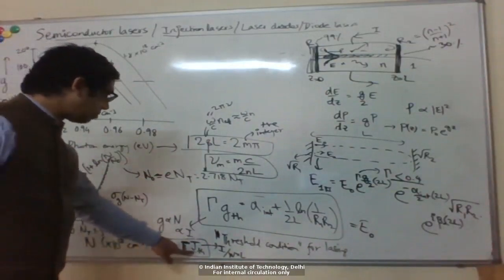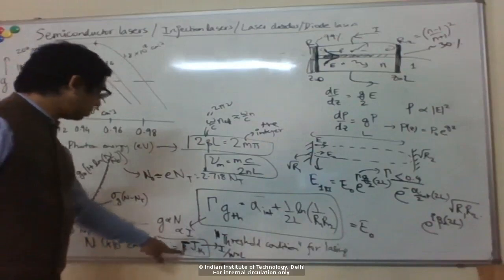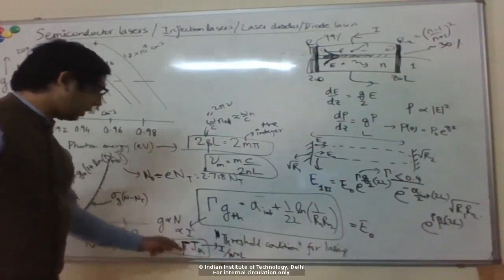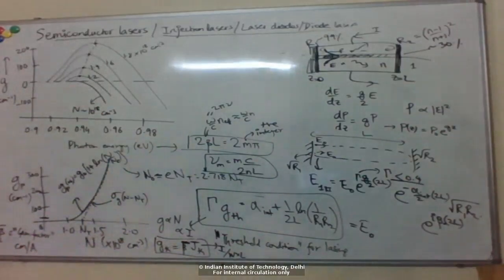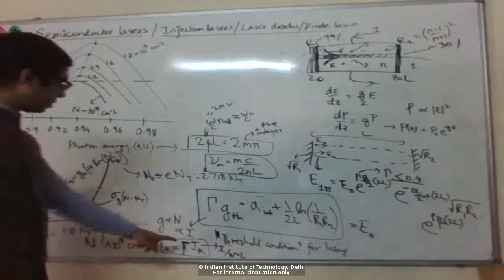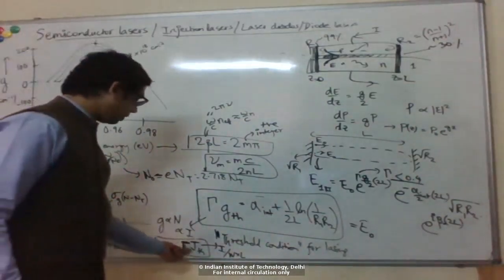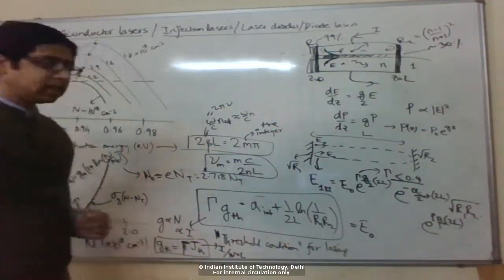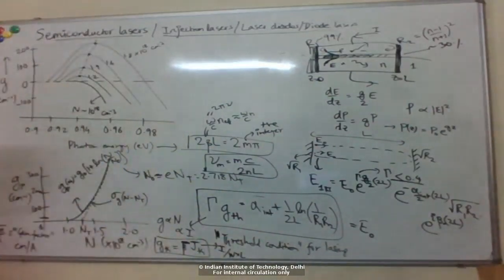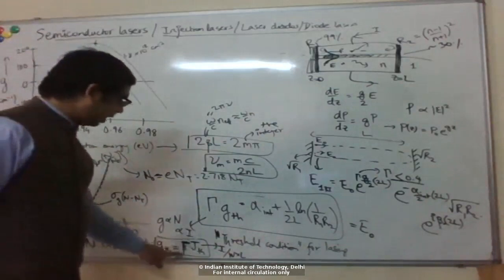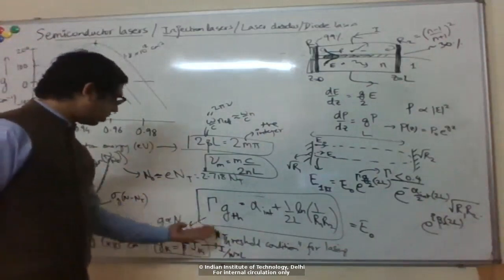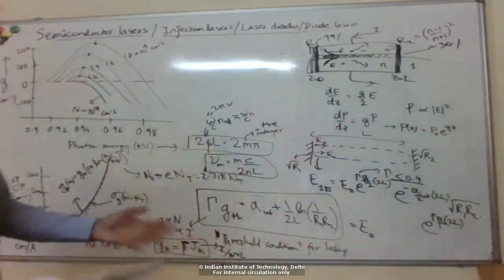This is amps per centimeter square, right? So you can see this is centimeter per amp. Again, this depends on my material and doping, etc. So the higher the value of this beta bar, I can achieve threshold at a lower current, or the device is more efficient.